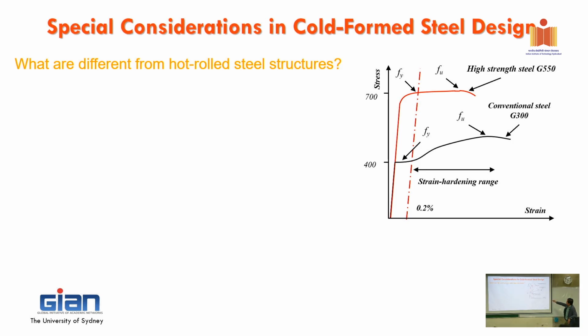This is the one I showed you already yesterday, right? This is a material property, typical steel property, showing the differences between hot rolled steel and cold form, high strength steel. So it's steel, so it's 200,000 of course, and 210 in the US for Young's modulus.